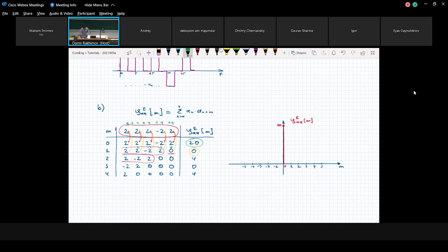Okay, and yeah, this left column specifies the difference in indices. For 1, the result will be equal to 0. Between indices 1, it gives us autocorrelation 0. For 2, it gives us 4. This is another pulse, with magnitude 4, amplitude 4. Then for difference 3, again 0. And for difference 4, it gives 0. All of the remaining ones will give us 0.